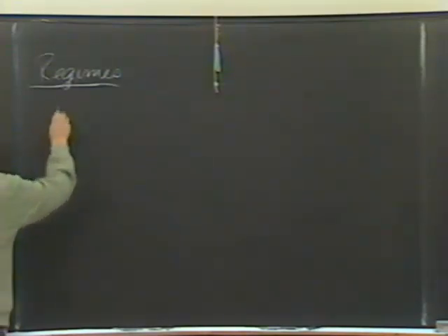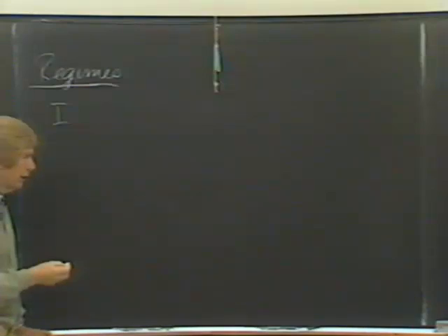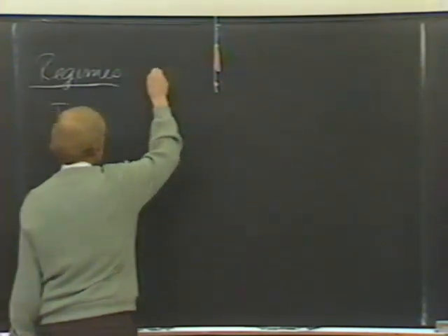Now with this kind of a breakdown, we can look back at that curve. The upper one I mentioned was the slurry situation. When aggregates developed and we had hindered settling, then the long straight section there, which is regime 2, aggregates collided with each other very frequently in the viscous layer.